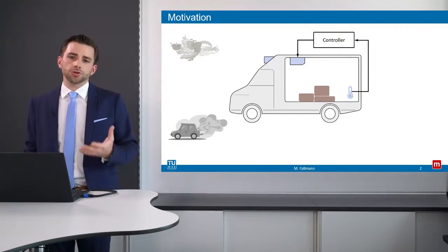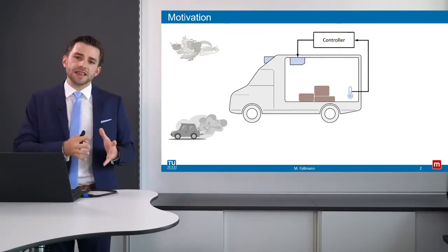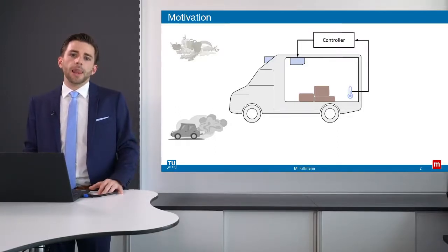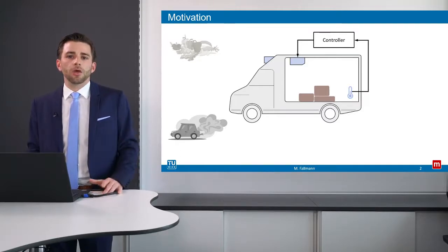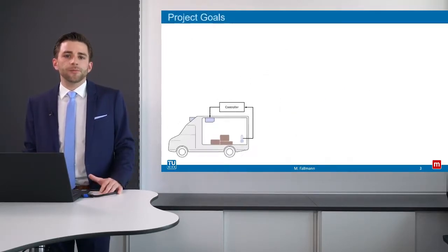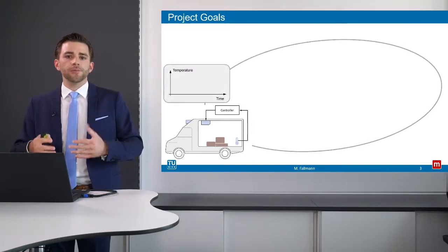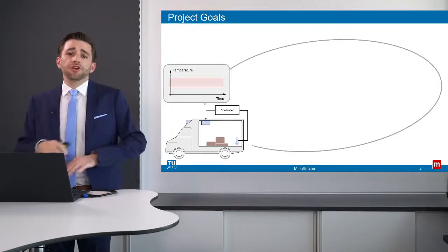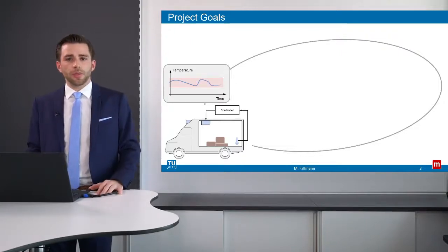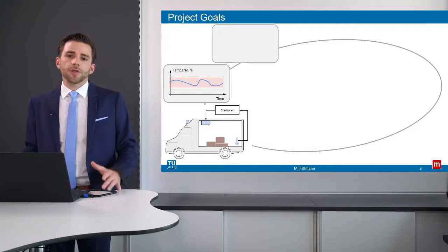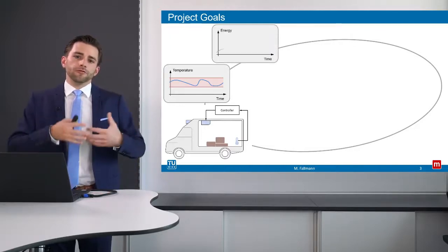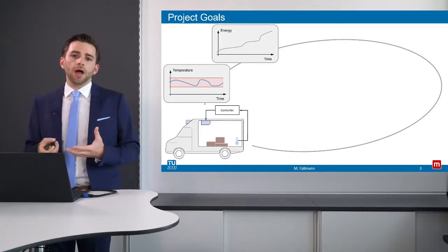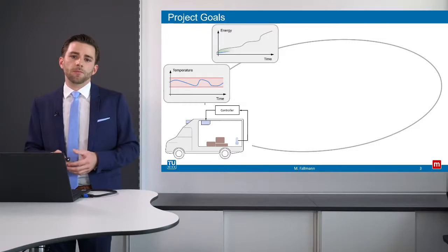In terms of control design, we have to translate and specify those two overarching goals. So let's look into the details. Firstly, the temperature of the goods in the cooling chamber should remain within a certain temperature range, regardless of any disturbances. Secondly, compared to the energy consumption of a standard control approach, here schematically depicted in gray, our algorithm should be more efficient.